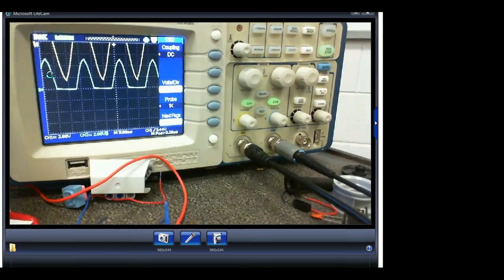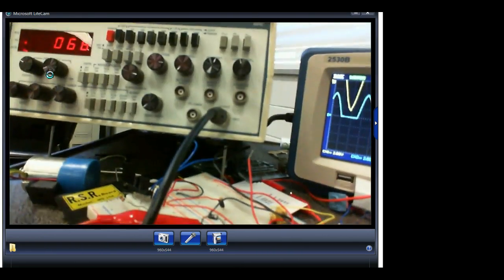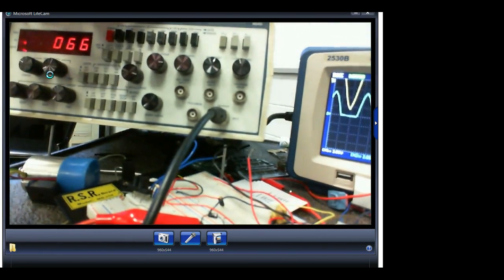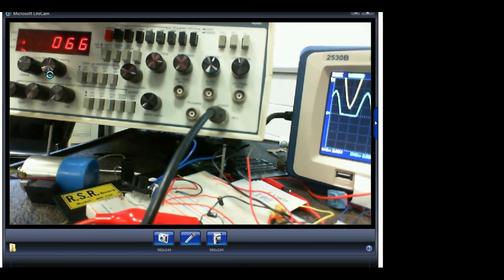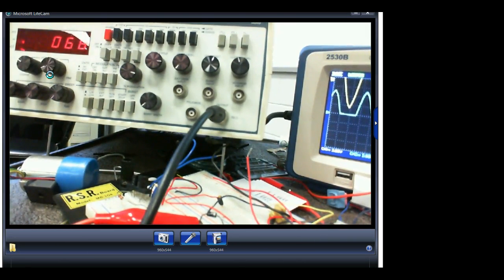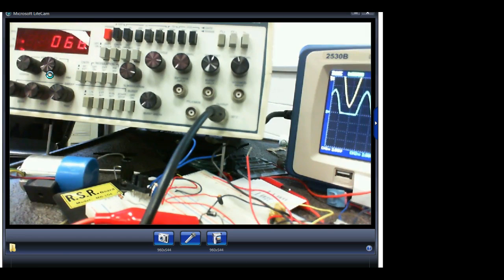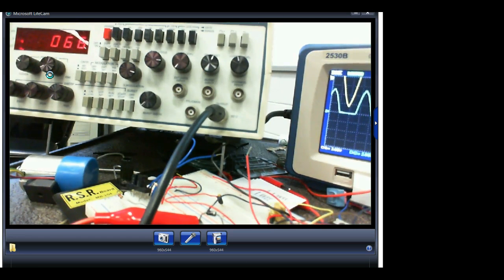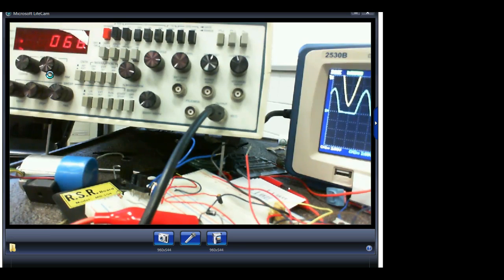So this guy here has a positive and a negative DC supply in it because it's generating AC, and it's doing it electronically, right? You understand that? So how can I generate AC? First of all, we convert it to DC. We have a positive supply on one side, a negative supply on the other, and now we can electronically control that with our amplitude.